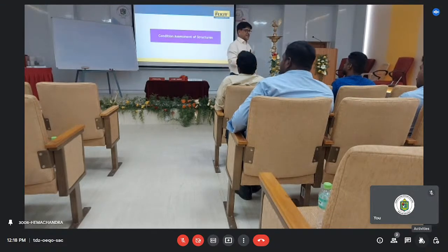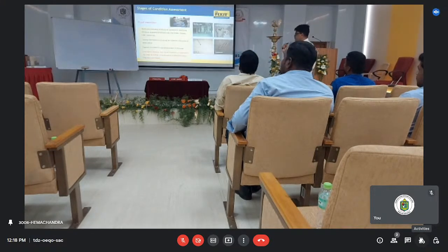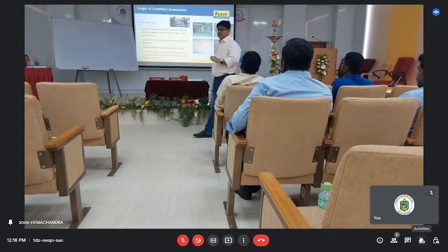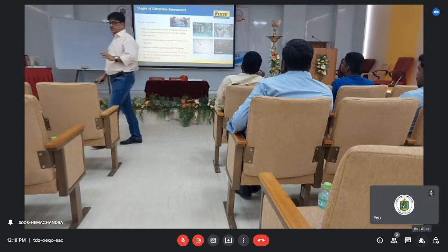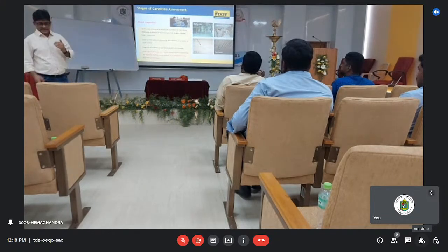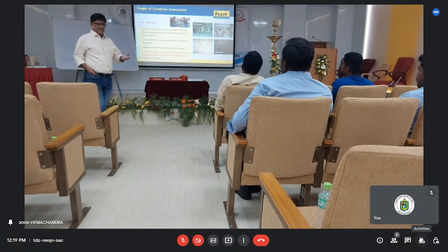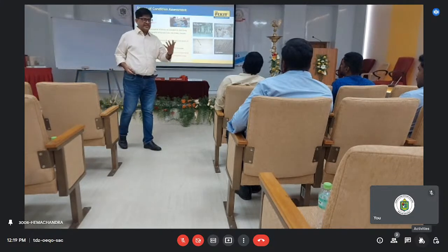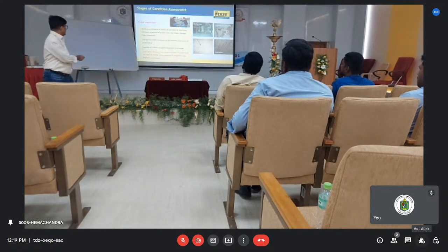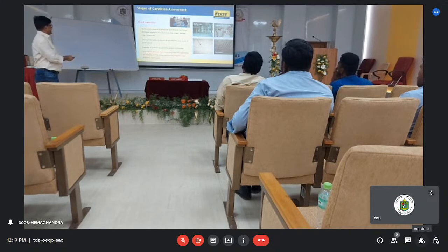So there will first be a visual observation. The first and very important thing is a visual inspection. In any condition assessment, a total visual inspection with a proper checklist has to be there. It gives a qualitative evaluation of the structural soundness, identifying the symptoms with your tools, different types of tools, can be chisels, hammers, whatever you are using. I'm not going into those parts. With the camera, you have to take photographs. Then information on the serviceability.